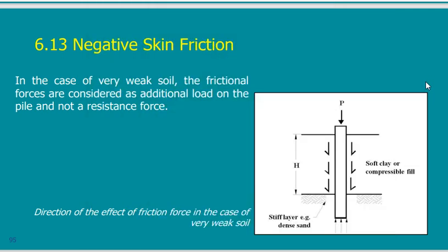This is exactly what is happening here. This is soil. And the soil is supposed to carry the pile. But if I have soil that is very, very soft, that will consolidate with time. So what will happen? Under own weight, it will consolidate. It will start settling down by own weight. So what will happen? I will put my pile here. The soil will get attached to the pile, and it will stay like this. It is now carrying the pile.